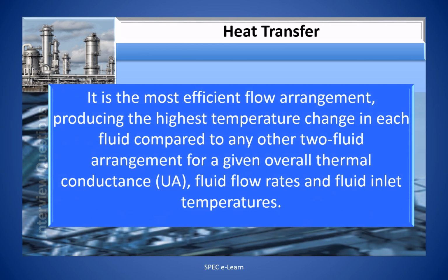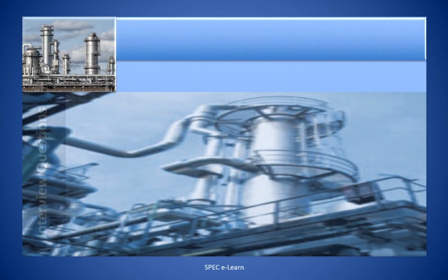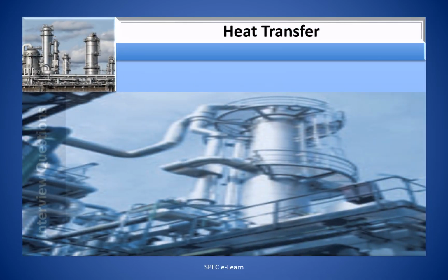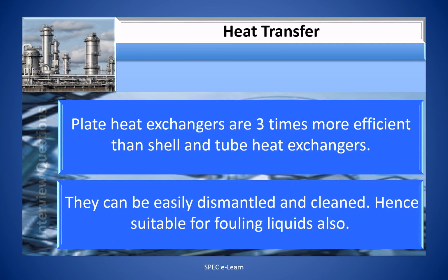It is the most efficient flow arrangement, producing the highest temperature change in each fluid compared to any other two fluid arrangement for a given overall thermal conductance, fluid flow rates, and fluid inlet temperatures. Plate heat exchangers are 3 times more efficient than shell and tube heat exchangers. They can be easily dismantled and cleaned, hence suitable for fouling liquids also.